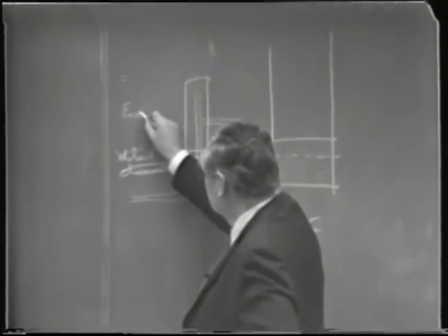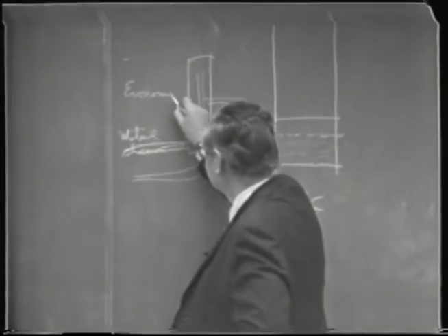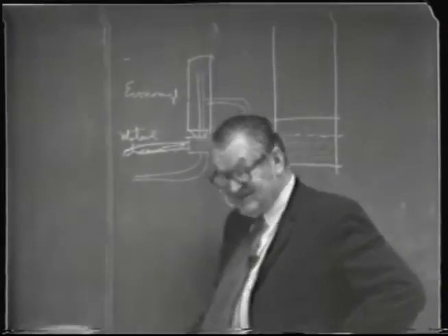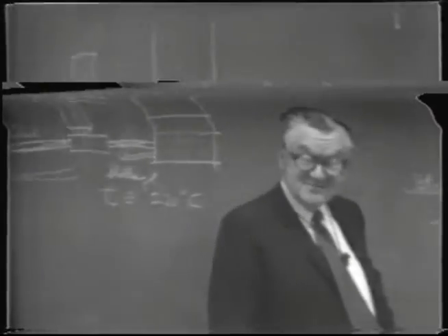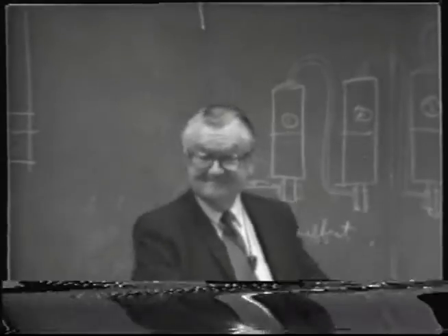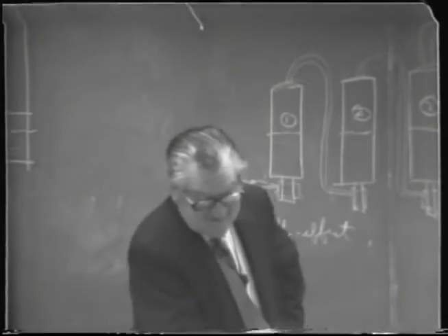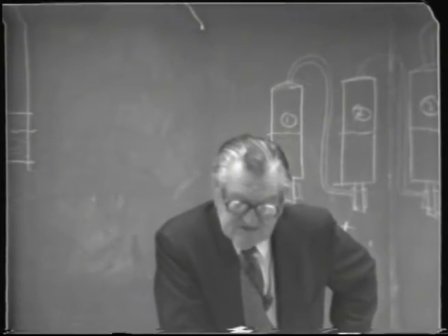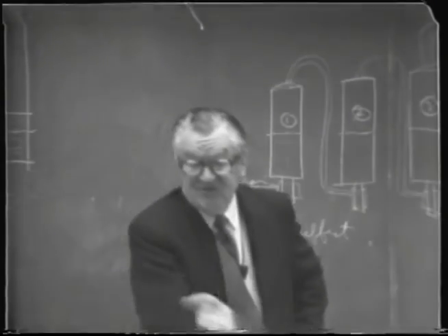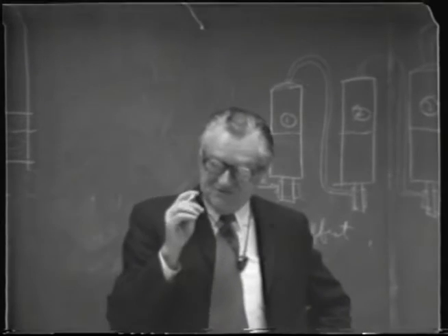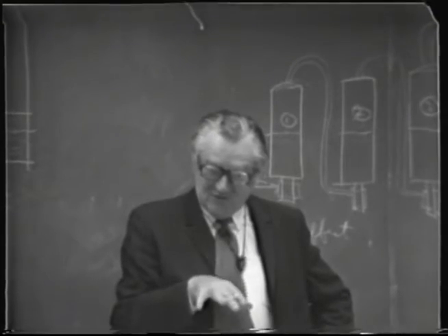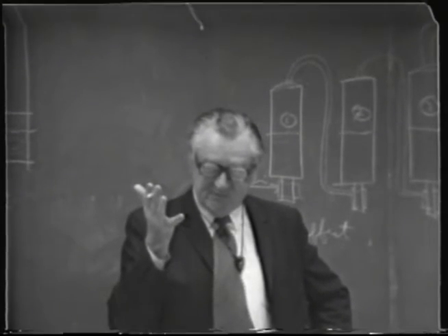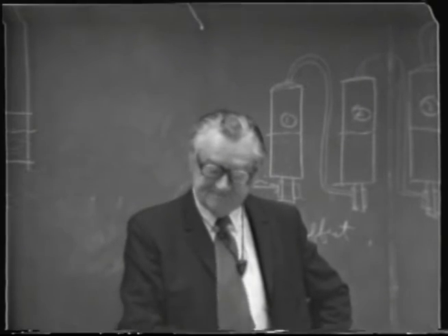Well, you're putting it in there with the steam, right? No, you're putting it in as a liquid, but you convert part of it into steam by dropping the pressure. It's sort of an example of flash distillation, if you want to think of it that way, although we didn't treat it from this standpoint. But you're flashing a liquid into a vapor by dropping the pressure.